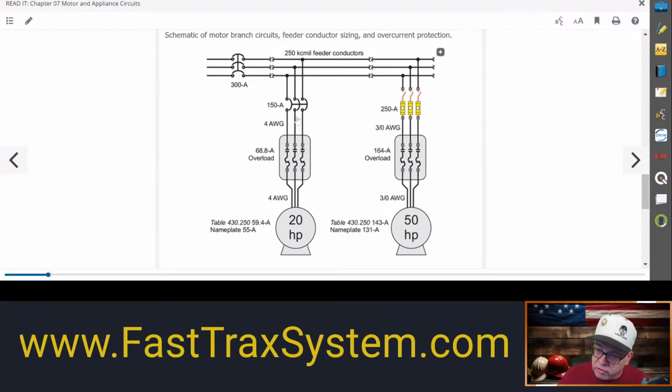This was the larger of the two short circuit ground fault protection. We took the larger, as it said, and we had already done this one. That's why we do all these strings. We've already done this one at the 175%, the same way that it says in 430.62. And it says you take the sum of the other motor that's in the group. All right, so this one's at 250 right here. We took that and we added the 59.4 amps to it. That gave us 309.4 amps. But what did it say back in 430.62? Okay, what did it say?